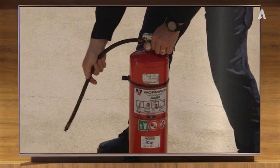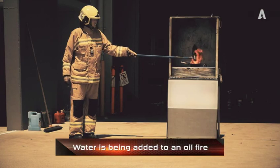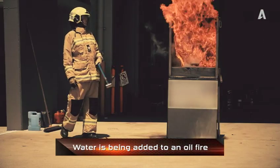This one is completely red, so it's a water extinguisher. The water extinguisher should not be used on a fire caused by electrical equipment. Can anyone tell me why? Because water conducts electricity? Correct. But also you should never use a water extinguisher on an oil fire because the oil will float to the top of the water and keep on burning as the water spreads.